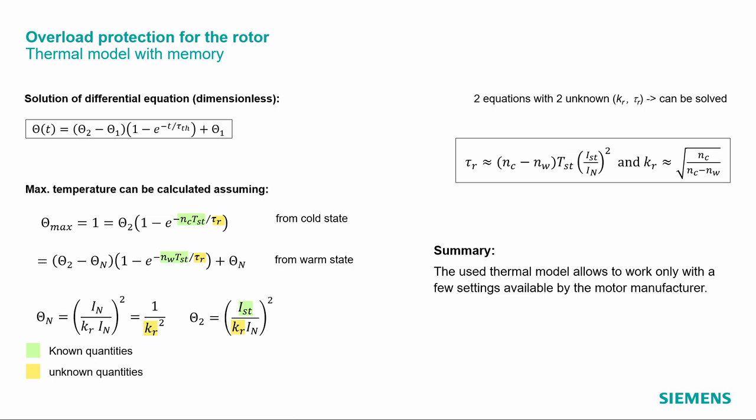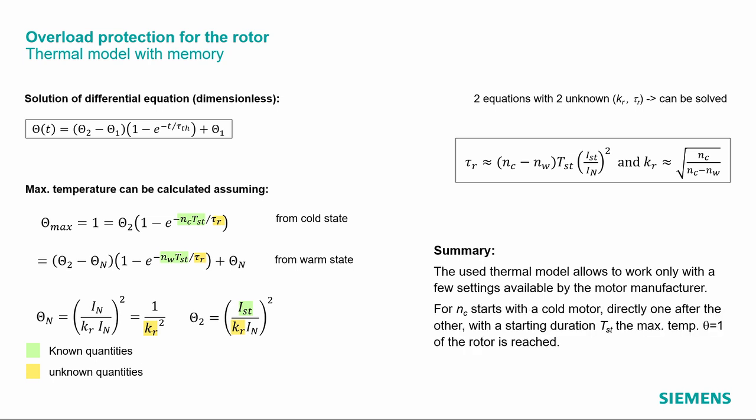The problem is that we don't get the data from the motor manufacturer, so we need to have somehow a practical approach to that calculation. The practical approach is to use that data, what we see here, and use a single body model instead of modeling, let's say, the motor with many thermal resistances and several thermal capacitances here. Okay, and as already mentioned, this is also described by the first equations.